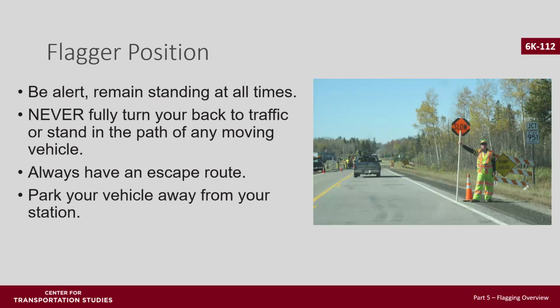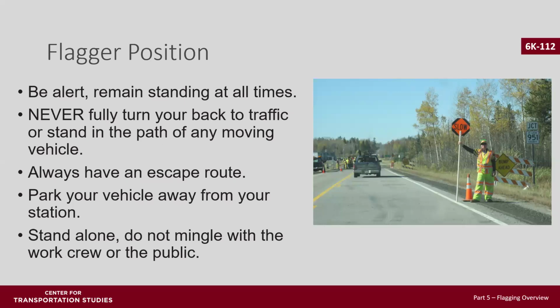Stand alone. Do not mingle with the work crew or the public. Make sure you're visible to oncoming, approaching traffic. Consider not standing where the sun is impeding visibility or in a shadow. Stand alone in a location that allows approaching traffic adequate time to respond, using decision sight distance tables. Make sure you can see approaching traffic for at least the decision sight distance.